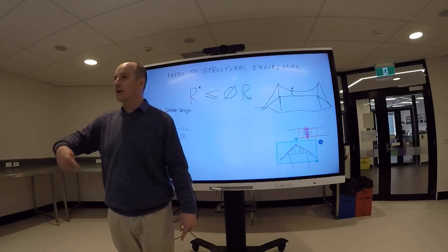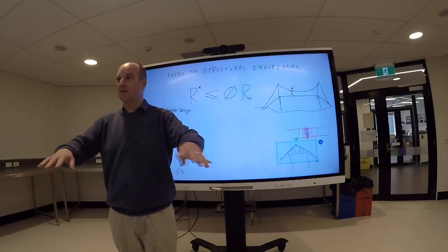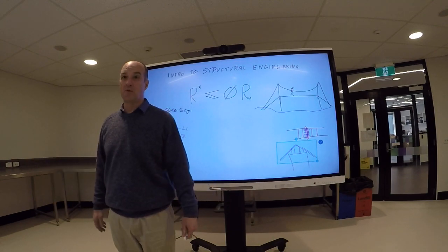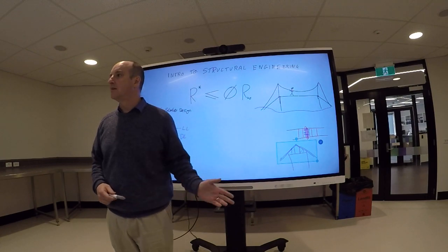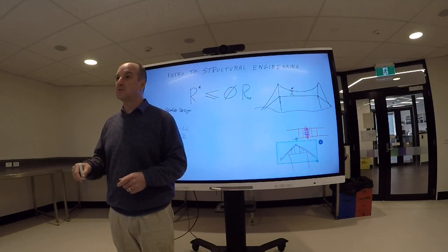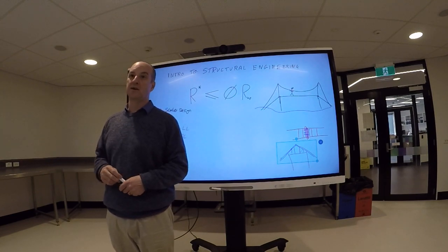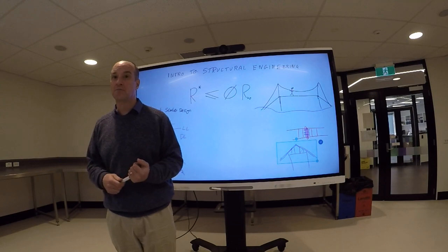So if we look at the loading in this room, if everybody is spaced out on a meter grid, that would be a live load of about 1 kilopascal. But you can imagine that you might get situations where more people are packed into this room than that. So this room is going to have a load requirement somewhat higher than 1 kilopascal. It's going to be at least four or five.